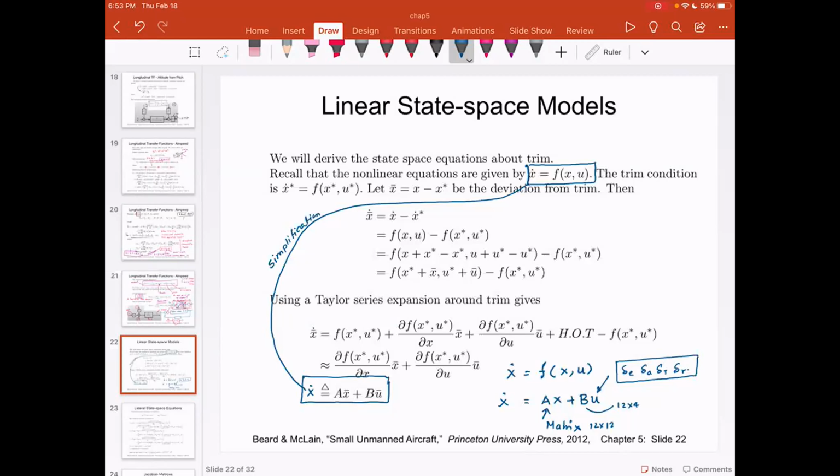So ideally, after all this simplification, I want you to look at the material that we discussed in the robotics one. A is nothing but the Jacobian of the given equations, and this Jacobian can be formulated mathematically or derived theoretically, but we use a Simulink function called linmod. That would help us to linearize the system approximately using numerical techniques, some optimization techniques.